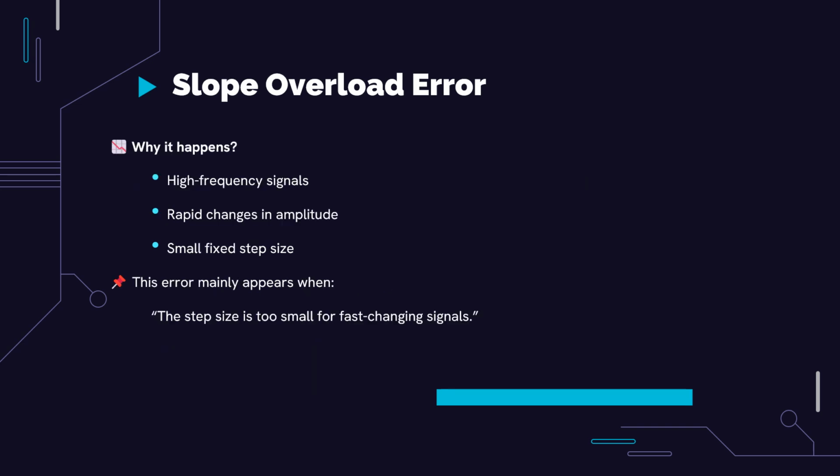Why does it happen? High frequency signals, rapid changes in amplitude, and a small fixed step size. The error mainly appears when the step size is too small for fast changing signals.